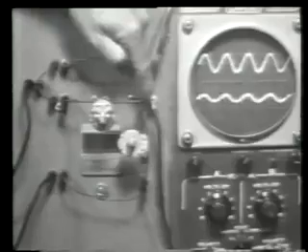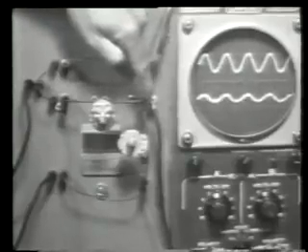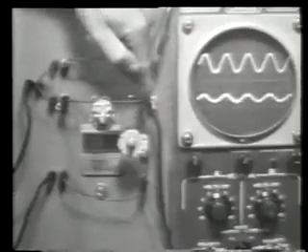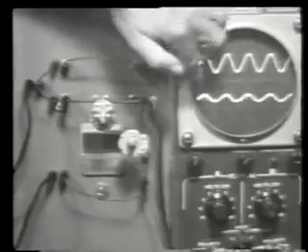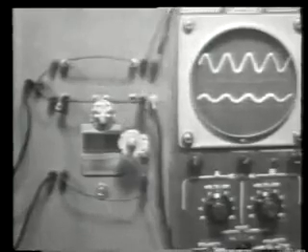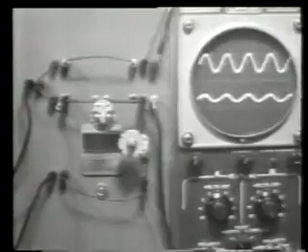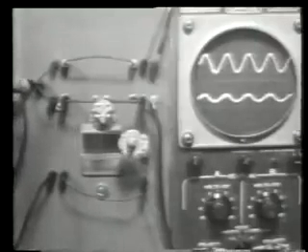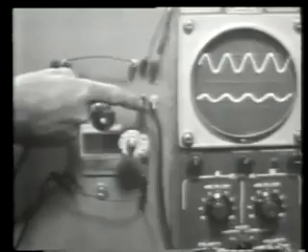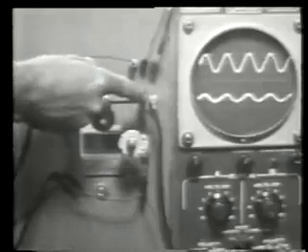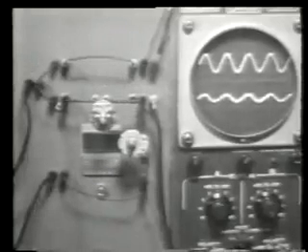Now this is the output of our trainer, so the tone will always indicate whatever is coming through the circuit. You'll also be able to see the output displayed on our scope, so you'll have two checks to determine the effect of our filter components on our output voltage. I think in this way you'll be able to understand the operation a little better. Now remember, the generator output, which is applied here, will go through the series component, then down through the shunt component to ground, and we'll be taking our output across the shunt component.